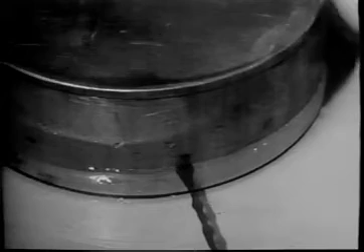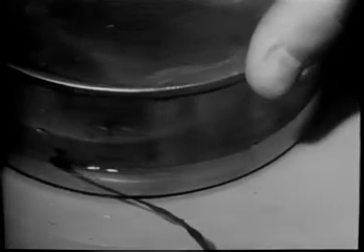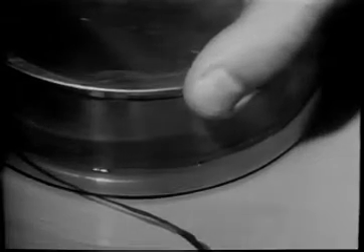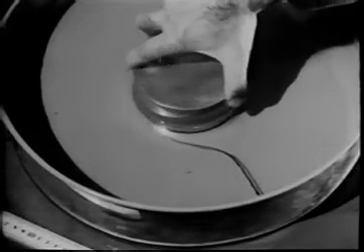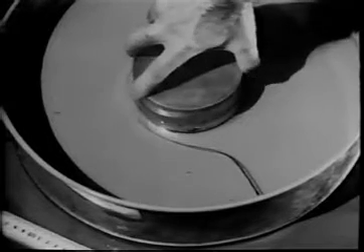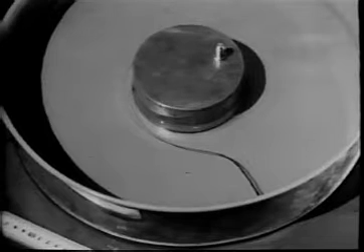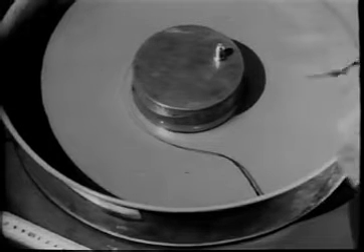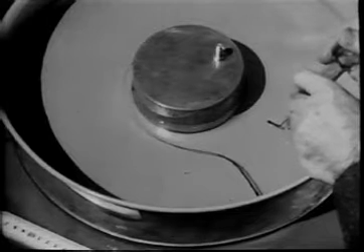The fluid immediately adjacent to the surface of the cylinder moves with the surface. It does not slip. Because of viscosity, the fluid farther from the cylinder also moves, but at lesser speeds as the distance from the cylinder increases. Let's see what this change of speed with distance does to a fluid particle which is initially square.